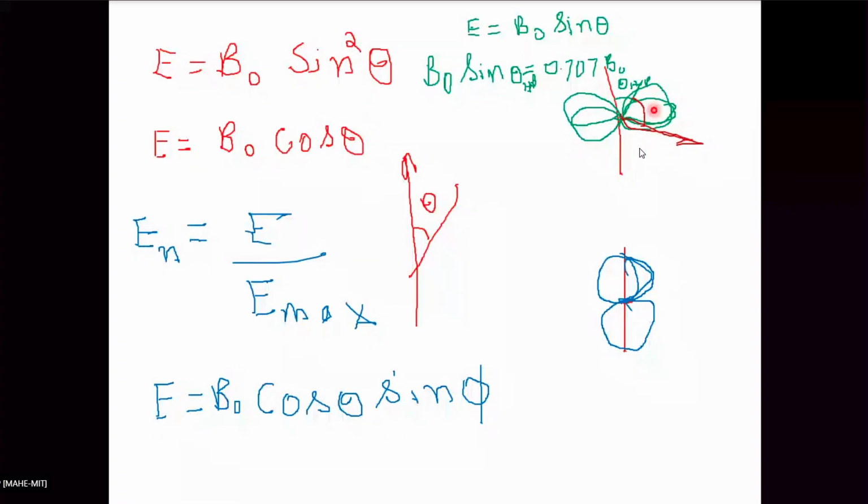In between the half power points we have the half power beamwidth. How do we get that? 135 minus 45 is the half power beamwidth, or 90 minus 45, into 2. Why into 2? Because it is symmetric. The pattern will always be symmetric. Okay, do you get it?